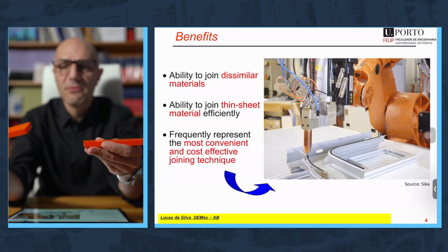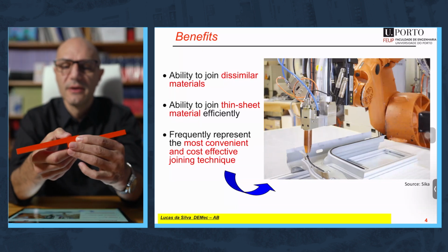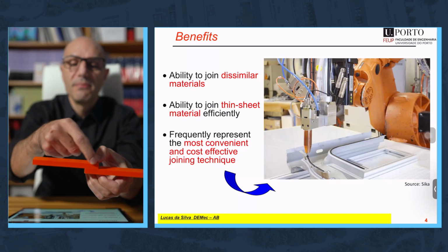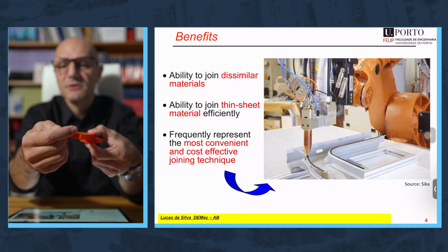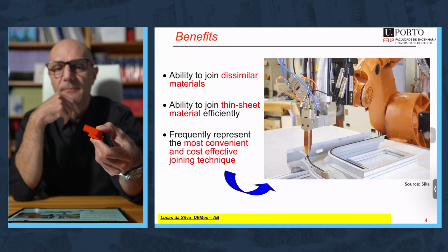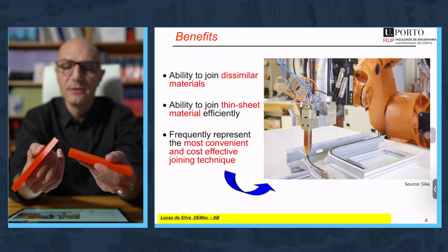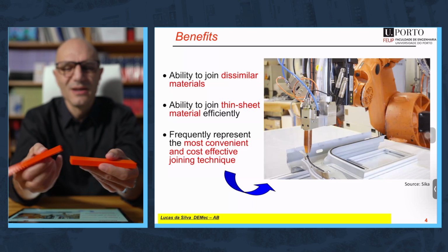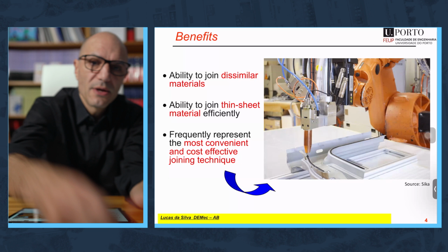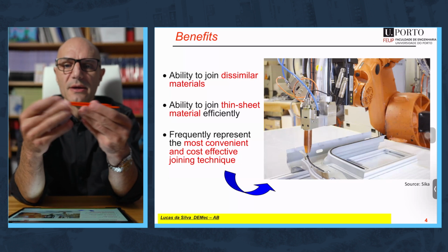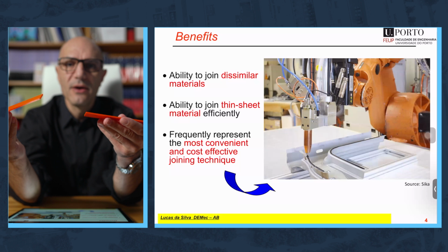You can think, okay, I can do an overlap for the adhesive and take advantage of a bigger overlap. The problem, even like this, the thickness of the substrate is still very, very high, and it will probably fail at a low load again in the adhesive. Doesn't really make sense. What makes sense is to use thin sheets. Again, if we do this, doesn't make sense. It will break in the adhesive, low strength.